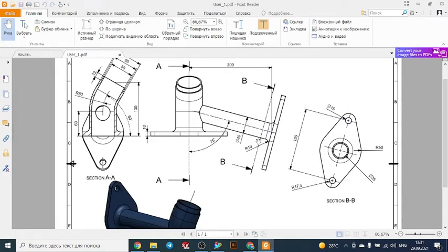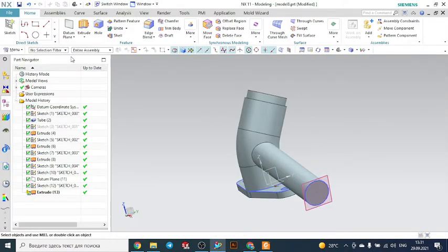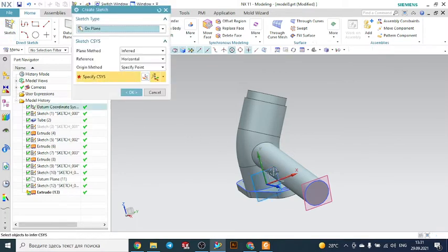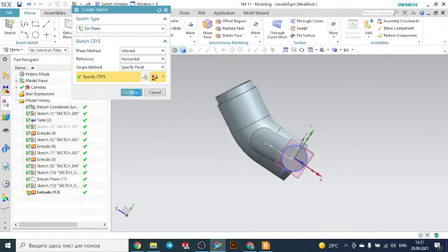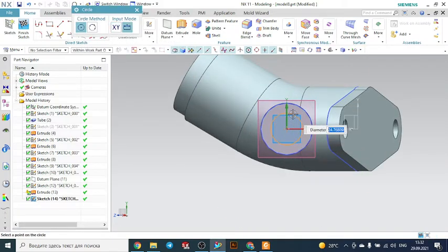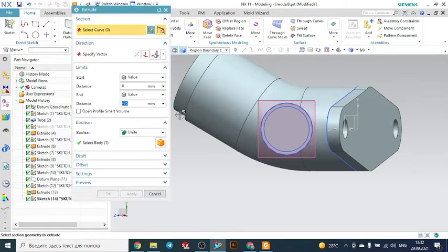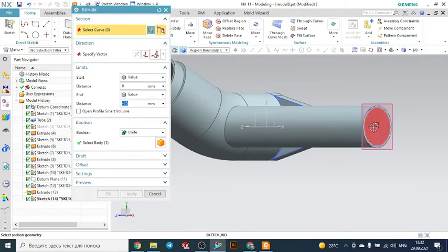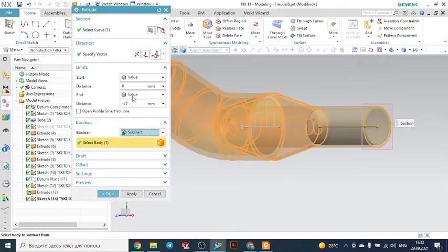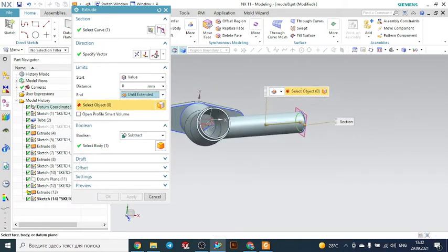So we'll make the hole now with the diameter of 35 millimeter. In order to do this, select this face, and select the circle with the diameter of 35 in this case. And make it extrude. Select the inner face here, and here the direction. Make it subtract firstly, and here select until the selected. In this case, select this inner surface.